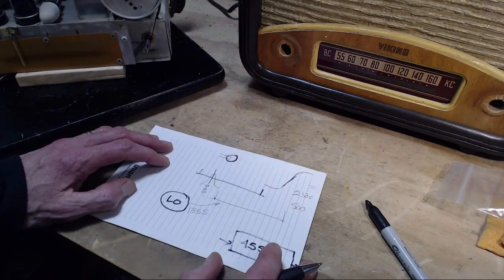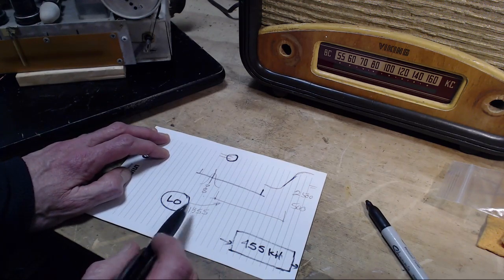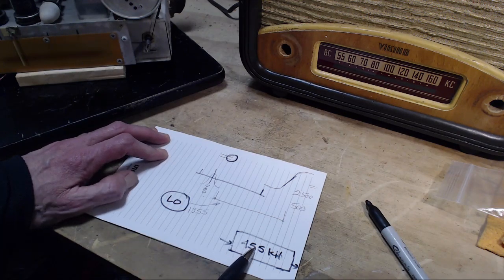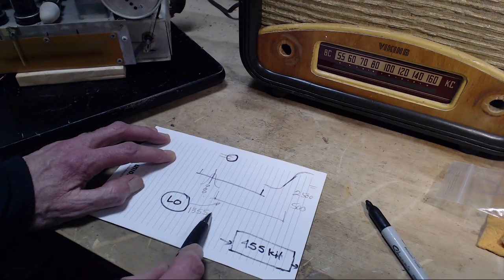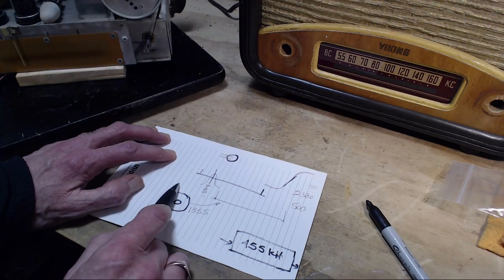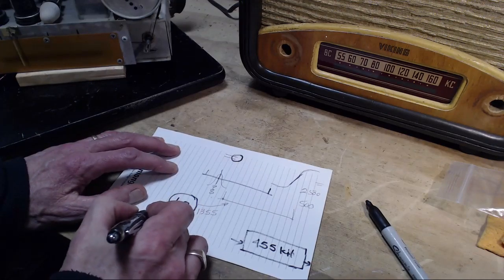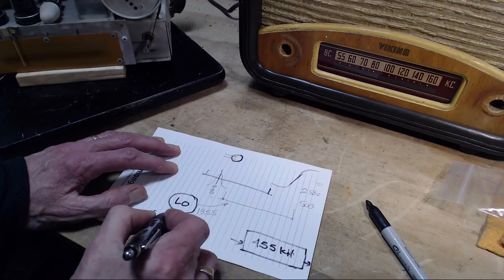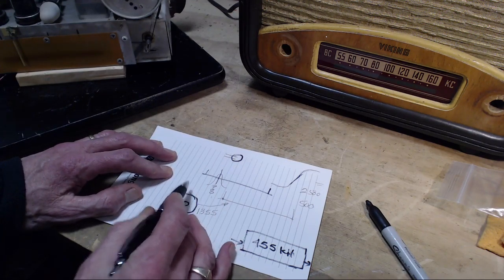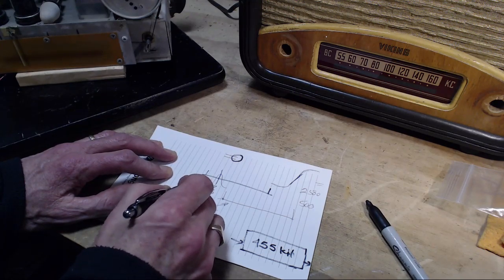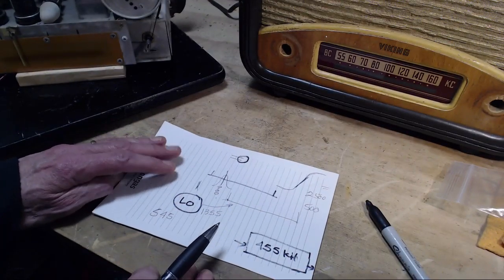Now here's where the image comes in. So I mentioned that if you want to take your 900 signal and turn it into a 455, you set the local oscillator to 1355. Couldn't you set it to 455 below? What would that be? That would be 545. What if you could set it to 545? So if we had a signal at 545, maybe here, pictorially, can't that be 455 away from there? And the answer is yes, it can.